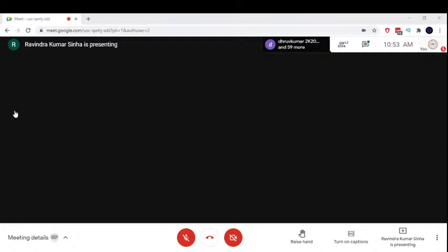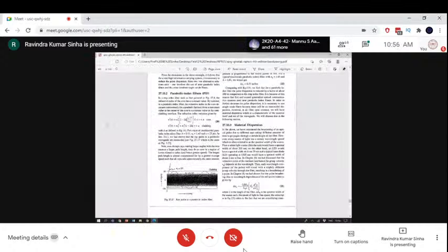So this is all about that. In this class, I started with the optical fiber. I derived the expression of the numerical aperture, how the light ray is moving, and what materials we are using. That portion I have done. Pulse dispersion, that is ray dispersion, is an important aspect for your numerical problems. So you do it.